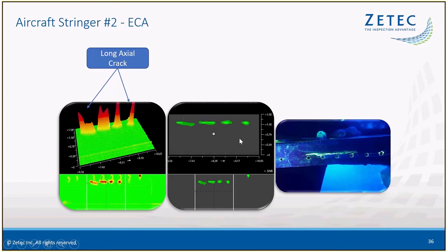So there was some stress that was occurring at each hole point, and it was creating cracks that were forming. And over time, if you were to monitor this, these cracks would probably eventually join together. But here you can see it on the color scheme with the C-scan, clearly showing the 4 cracks here.